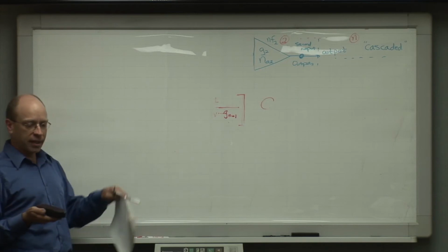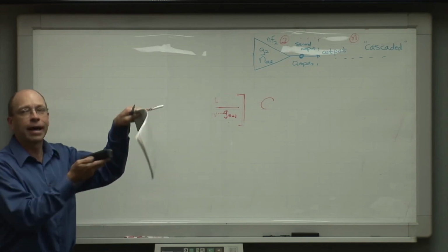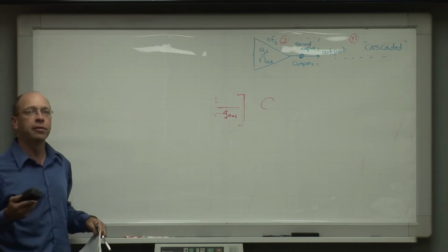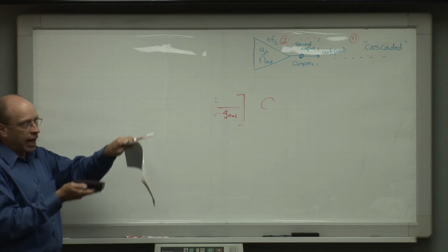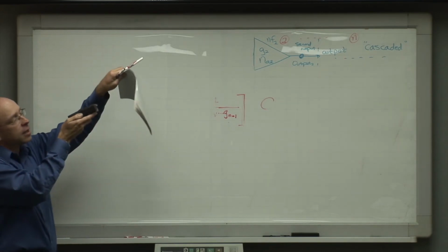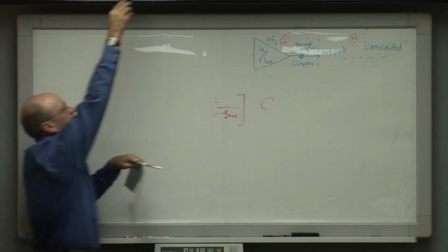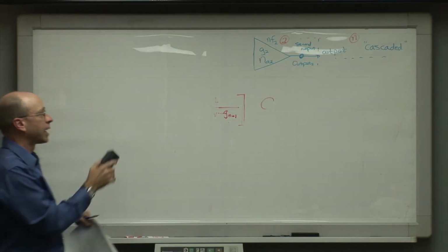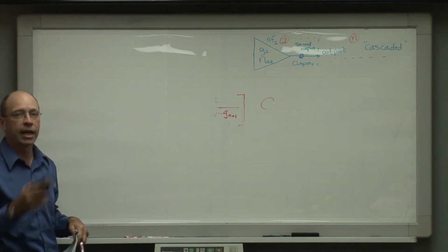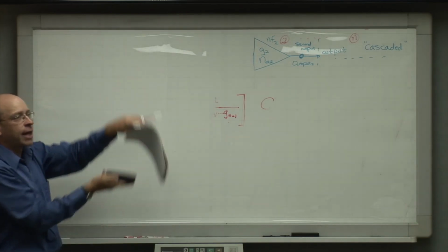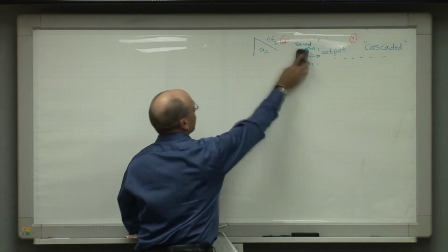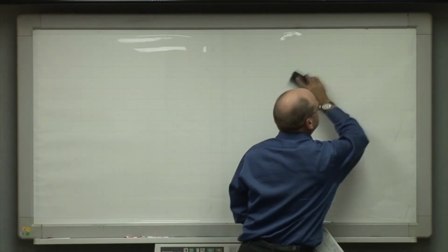is that because the gain and the noise are both basically going up together, plus a little bit of added noise, at a certain point all you're doing is making the signal and the noise go up higher and higher and higher like this, while you're approaching the top of the dynamic range of your measurement system up here. You're eating up that dynamic range, and in fact you're getting no benefit in terms of seeing your signal any higher out of the noise than you would have had you been using a lower gain figure. And yet this is a mistake which people have been known to make at one time or another, imagine.